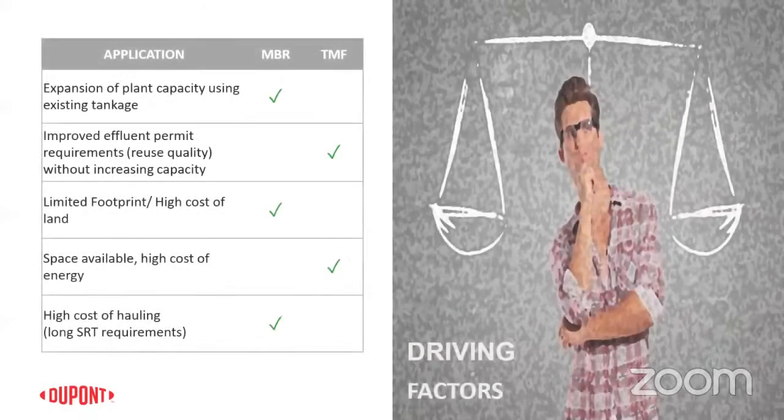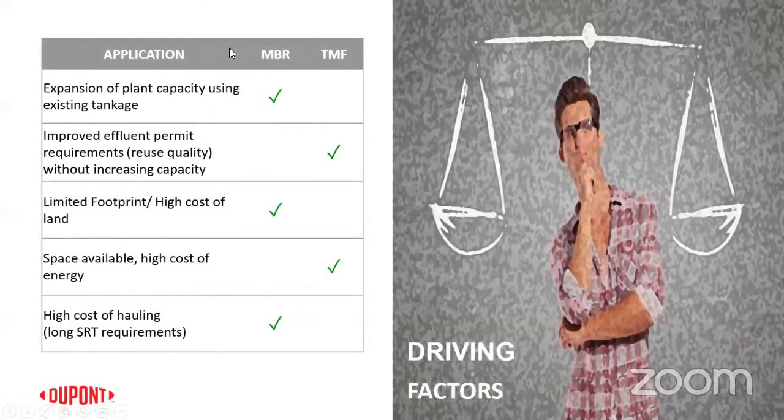Now, there is always this question coming up: when should I go for MBR and when should I consider traditional membrane-based filtration? Traditional membrane-based filtration, as in you already have a biological treatment like settling, aeration, secondary clarification. Is it fine if I just have a UF, then post-treatment if required, or should I go in for an MBR system, in case there is an expansion plan for the same capacity?